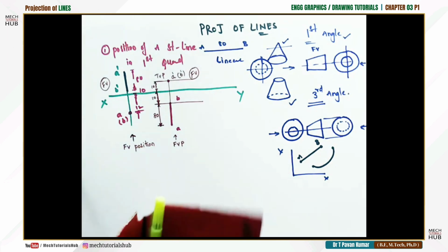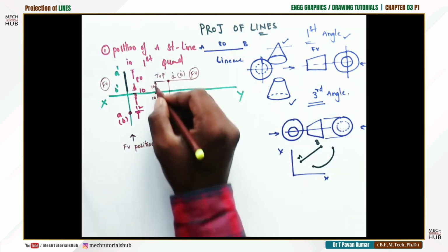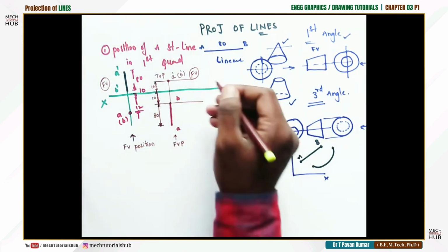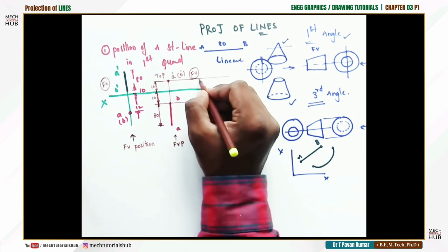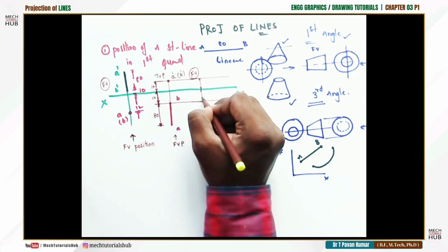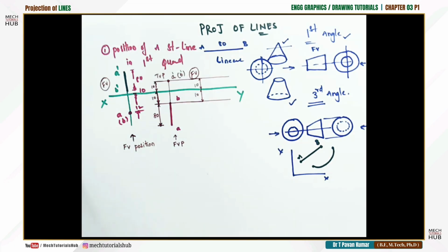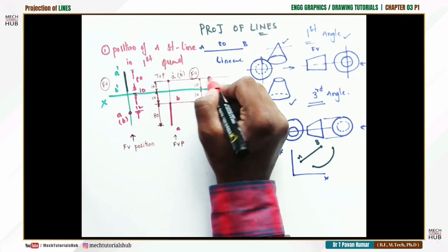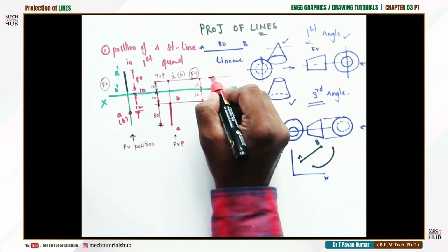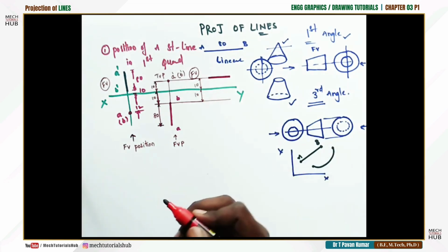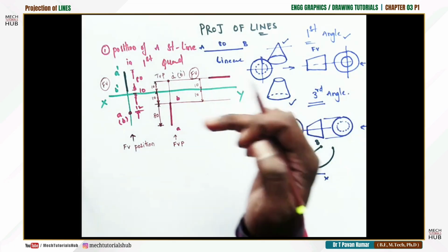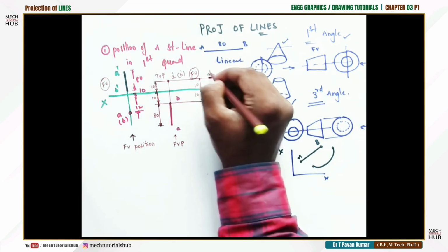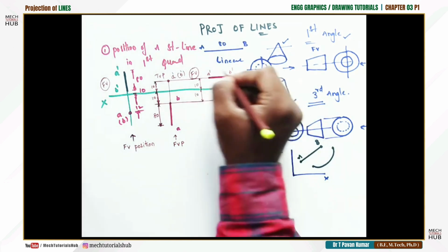If that is the case, what I try to do, since 10 mm was already given for the second solution, I'll consider the same distance. I'll extend the locuses and make a mark of dimension line 10 mm. Now I could see the true length 80 mm. 10 mm away I'll start drawing the line which is of 80. After drawing that 80, this 80 is your front view. Maybe this end is A prime, this end is B prime. Complete length is 80 mm.